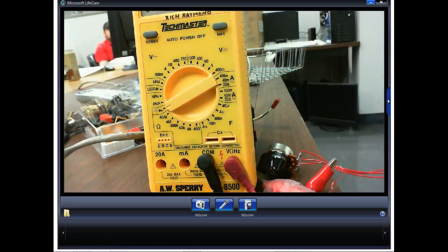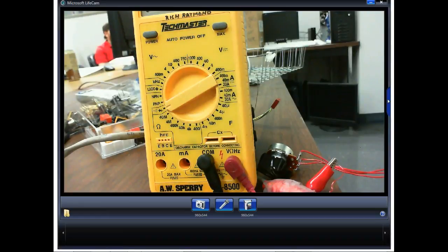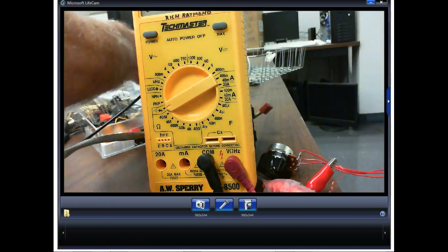Check circuit breakers. We can check anything that tries to break the circuit. We check a switch to see if it's good or bad. We can use our ohm meter, but if we use a continuity checker, we don't even have to look at it because this tells us when we have less than a certain amount of ohms, right? You understand? So if I wanted to check a fuse, which is basically supposed to be a lot like a wire, then I can come up here and I can just, so I know that wire's good, right? You understand? And we trace wires all the time.